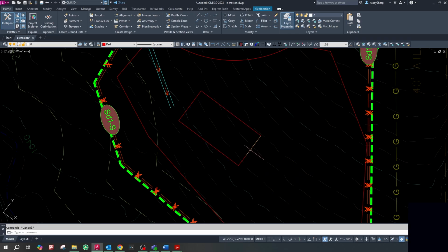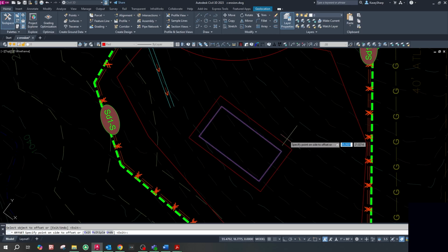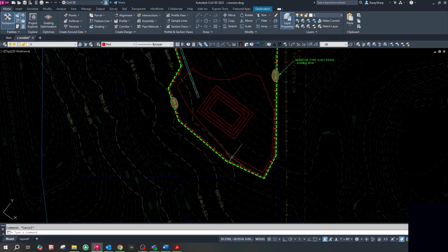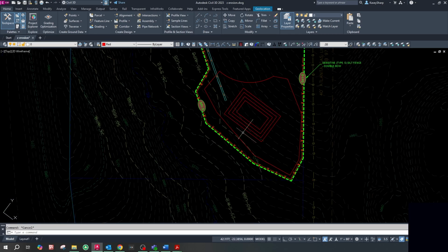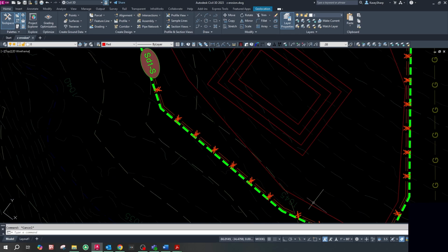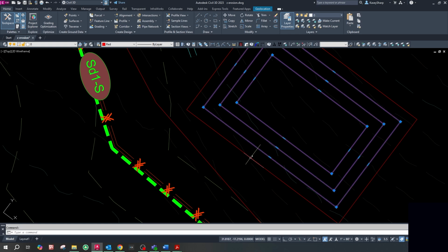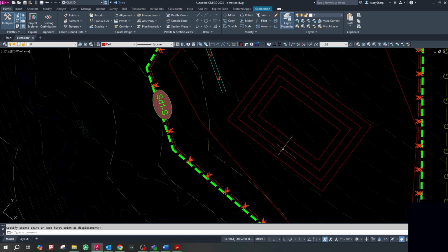We'll work with that. So now we are going to offset this guy 4 feet, just like grading in a detention pond. So I'm just going to offset this guy for 2-foot contours. And then again, the bottom of our pond is that 1046, which is this contour right here. So we're just going to go ahead and set the bottom of the pond at 1046.